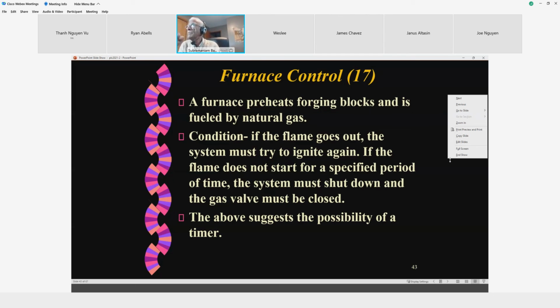Get the ignition back and make it ignite again for a period of time. The ignition should be coming in only for some programmed time, 6 seconds, 5 seconds, or whatever, right? So first time it went for, let's say, it is programmed to go 6 seconds, but at the end of 3 seconds, the flame came on. So it should automatically quit when the flame comes on.